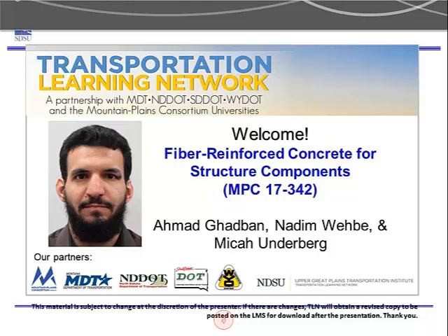There's also a lack of information about new fiber products that have been introduced in the market recently. So this presentation will go over results of a literature review and also some DOT interviews, a summary of 21 mixed designs, and also suggested guidance for fiber reinforced concrete design, construction, preparation, and testing.